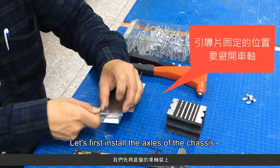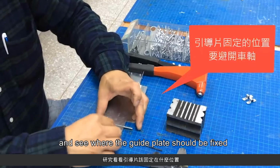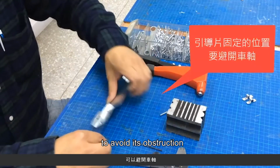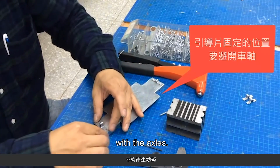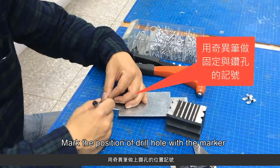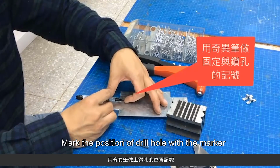Let's first install the axles of the chassis and see where the guide plate should be fixed to avoid its obstruction with the axles. Mark the positions of the drill holes with a marker.